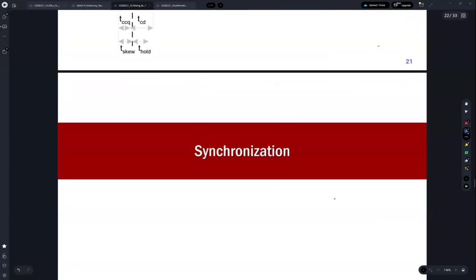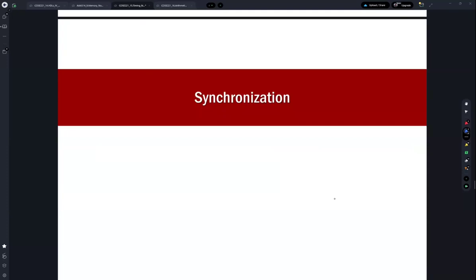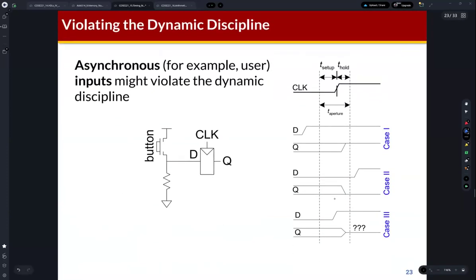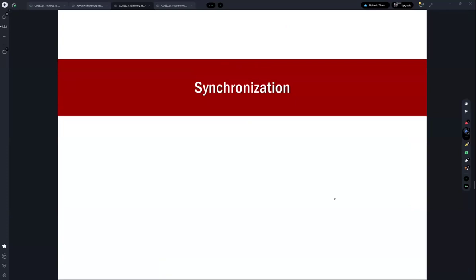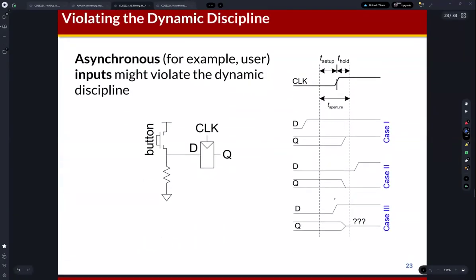And then I will briefly explain about synchronization. So far we analyze the timing of the system inside of a system. It means we just consider signals like the clock signal and the reset signal, which are generated in the system, and we handle the signals inside of a system. Then what does that mean? In reality, we need to consider the signals from outside of the system. For example, I use this pen and click the screen. So this is the outside signal, right?